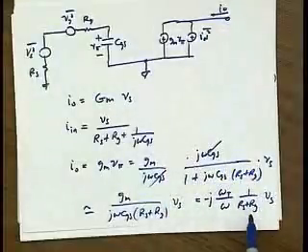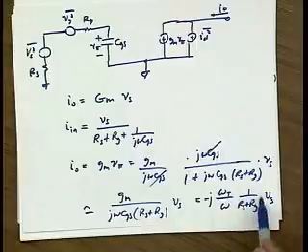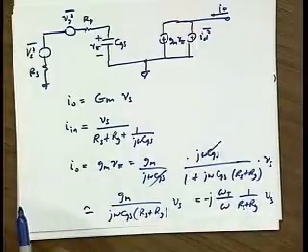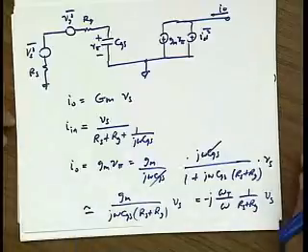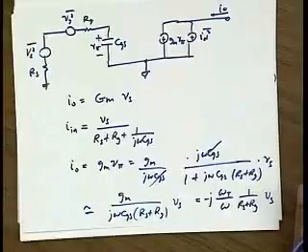So it's interesting to see at high frequencies the GM of the transistor effectively is a ratio of omega t to omega times basically 1 over the source resistance, assuming Rs is bigger than Rg. Okay. Now this way of thinking is going to come in handy later on.